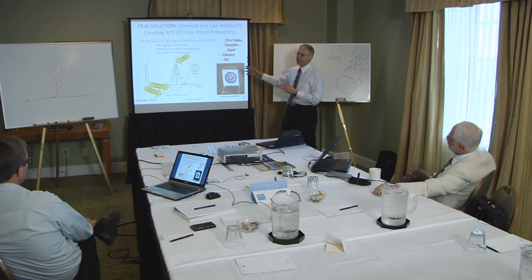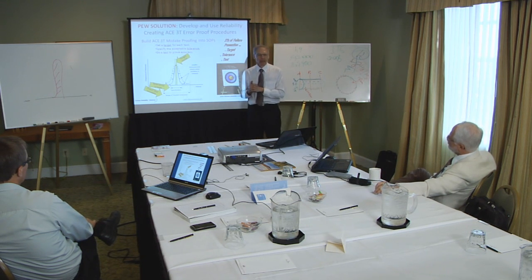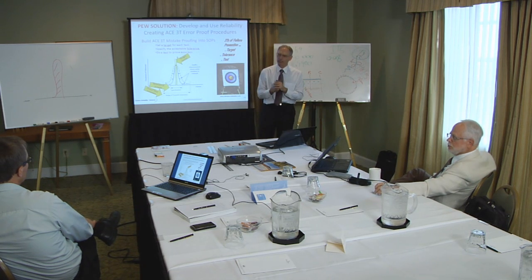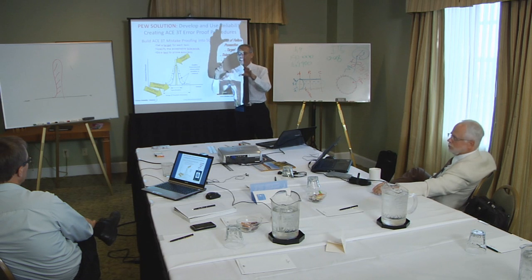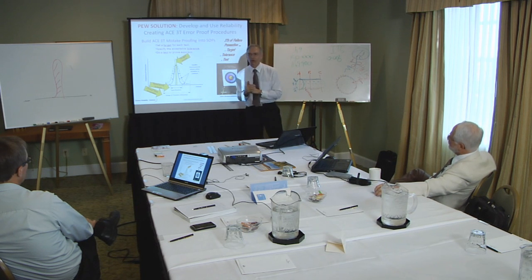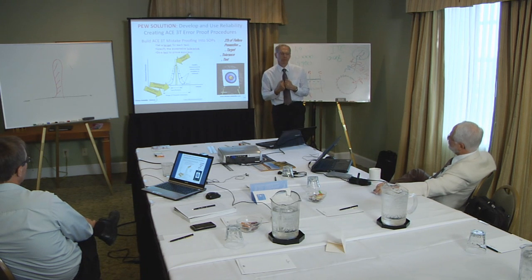So I've got to have the customer understand what questions to ask. Your specifications, what is your IT grade on your components? How do you control the manufacture of your shafts? How do you get roundness of your housings? How do I know that your bearing in that machine isn't pinched? If I pinch that bearing with an out of round housing, I'm going to have high stress in that bearing from day one. So once we know what the right questions are to ask, you will ask the right questions. And if the answer is the wrong answer, thank you very much, I'll go to somebody else next time. And you will, because there's so much money sitting on the table that is so easy to pick up.